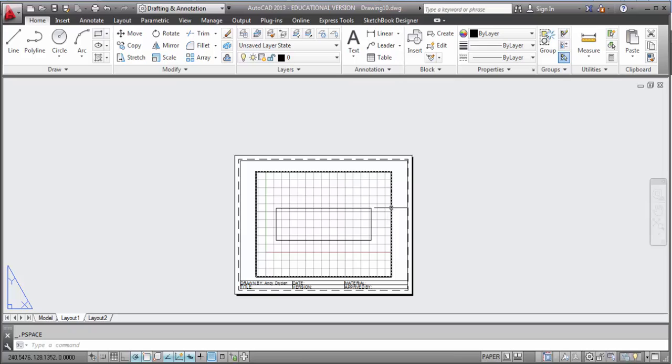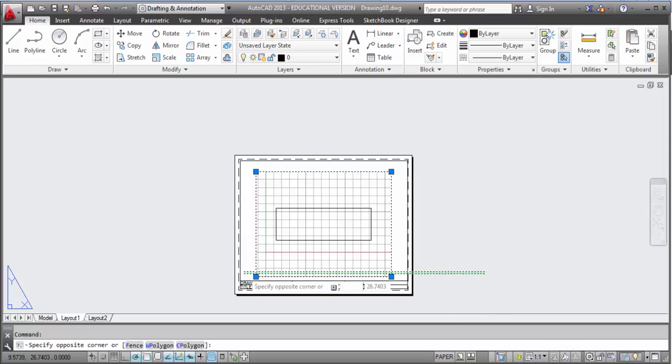If I want my viewport scale set to 1 to 1, which I have down here, that allows me to print the rectangle that I drew at 1 to 1 scale, meaning that when I print this, it will print out exactly 150 millimeters long by 50 millimeters tall. If I had drawn this in inches, I would have to use a really, really funky scale factor on my viewport window here. There are many ways to do this in AutoCAD. I find this to be the most productive way: take your inch template and do the process I've just done to change it to be metric.